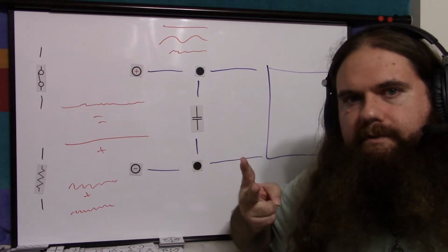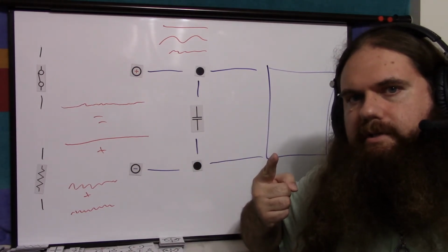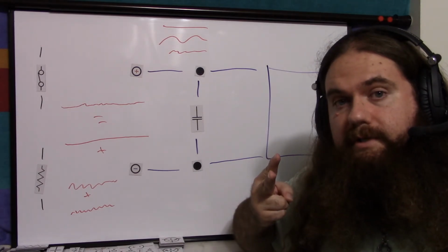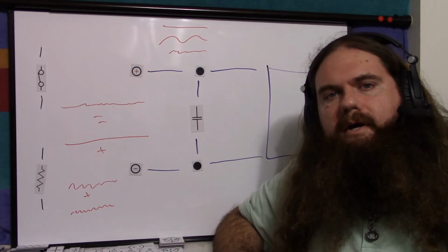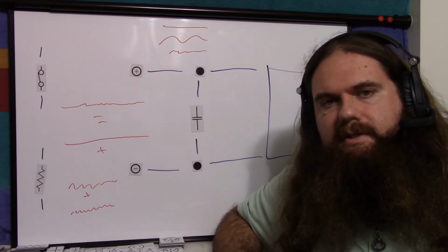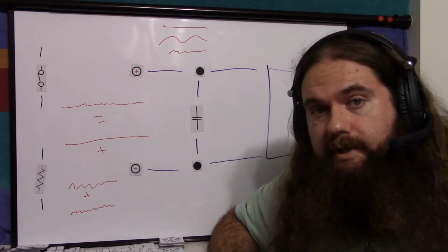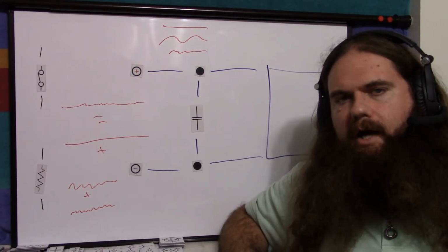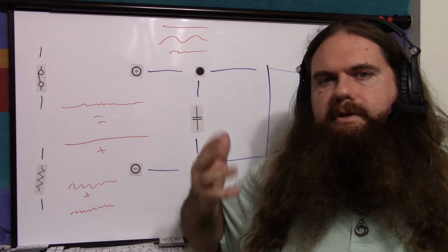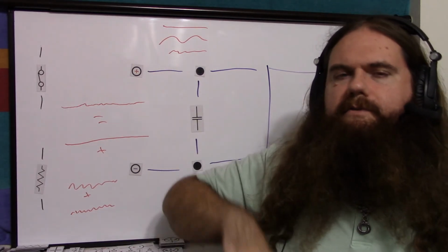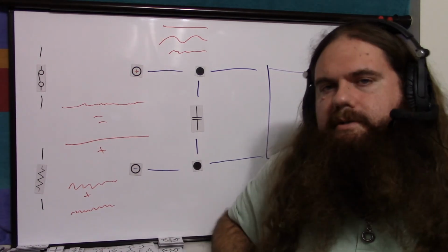It's a capacitor and a resistor. If you measure over the capacitor, it's a low-pass filter. If you measure over the resistor, it's a high-pass filter. Your time constant is R times C, resistance times capacitance, which magically works out to seconds. 5 times that number, 5 times R times C, is when we say it's fully charged or fully discharged. And that's all you need to know.